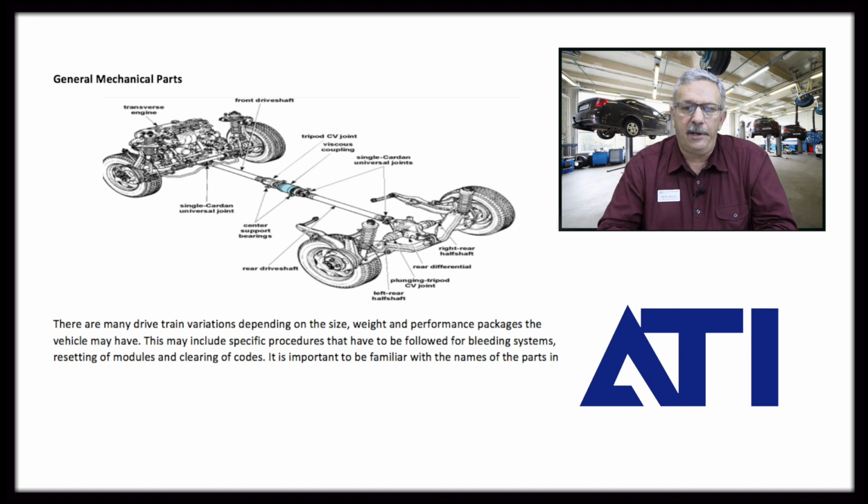Other things that are going to be really important here are how you bleed the brakes. What is the process that has to be followed, especially if you do work with anti-lock brake systems? Very specific bleeding processes have to be used. Depending on the vehicle, if you get into the cooling systems, if you don't bleed the cooling system in a very specific way, you can lock it up and create excessive heat in the engine, and we can burn an engine up. So again, I need to know when that system has to get bled, and the only way I know that is by following the manufacturer specifications.